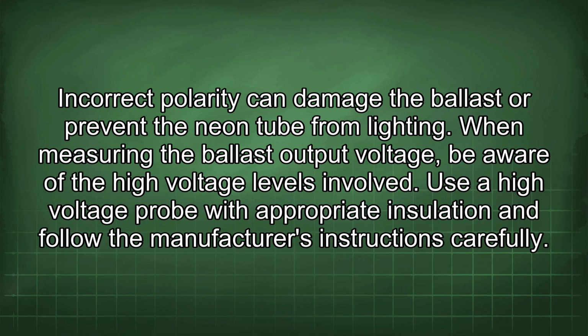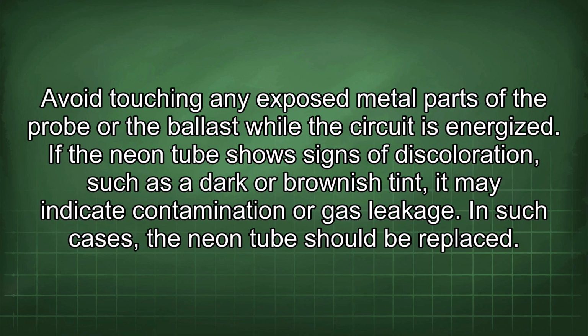When measuring the ballast output voltage, be aware of the high voltage levels involved. Use a high voltage probe with appropriate insulation and follow the manufacturer's instructions carefully. Avoid touching any exposed metal parts of the probe or the ballast while the circuit is energized.